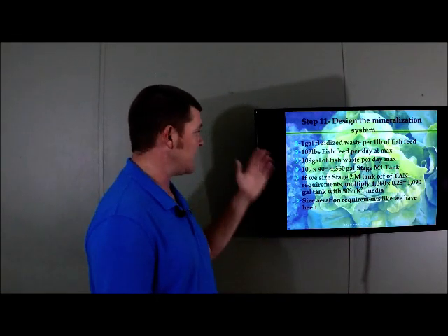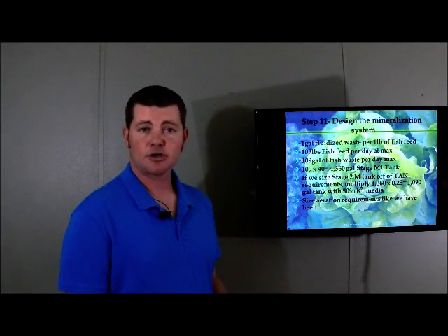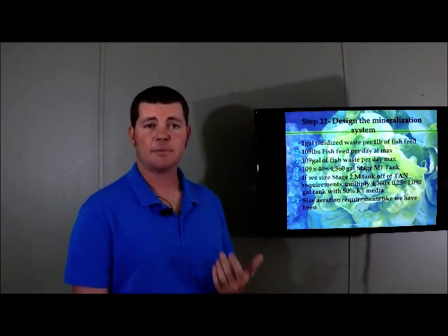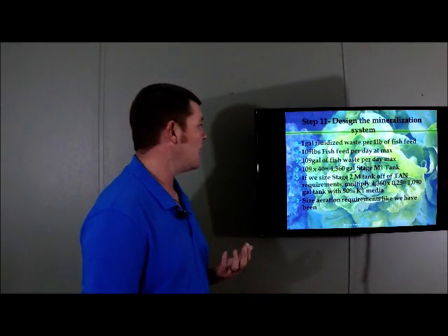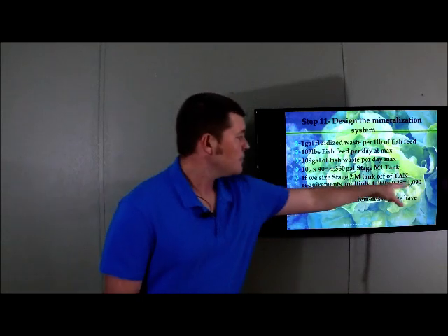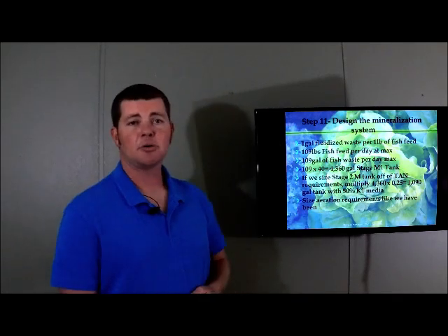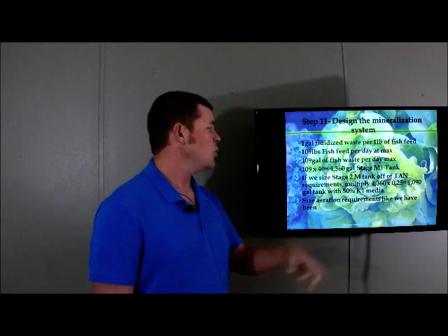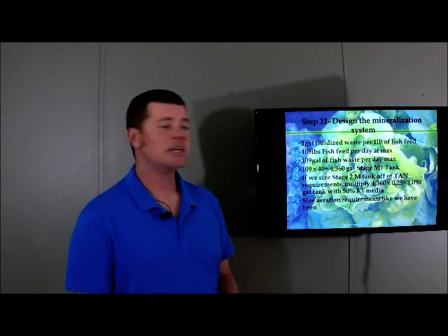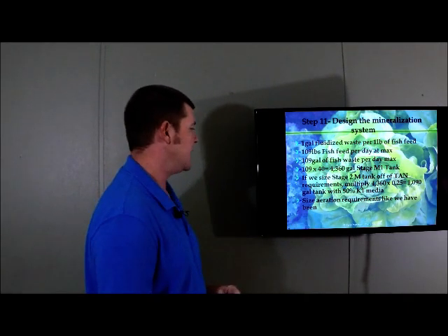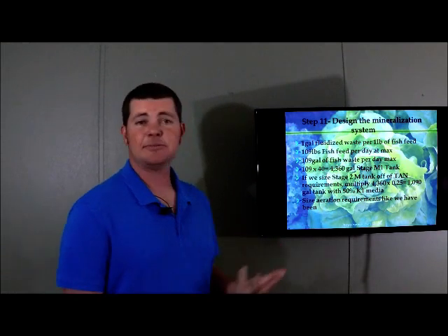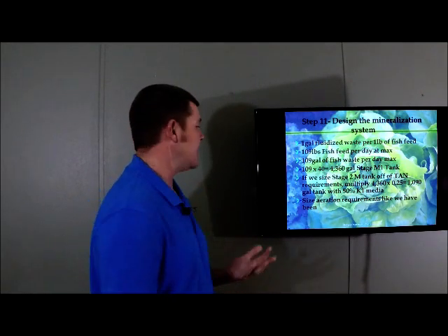Since we're using high levels of filtration, we're removing roughly 25% of that solid mass, so we multiply it by 25%. If this was only removing 15% of the mineralization, we do times 15, okay? And that helps us size based on the ammonia coming into that tank.